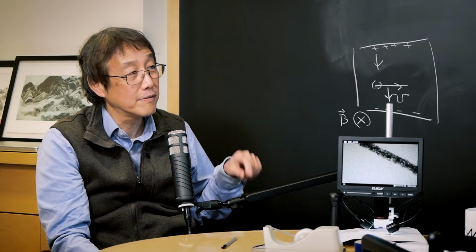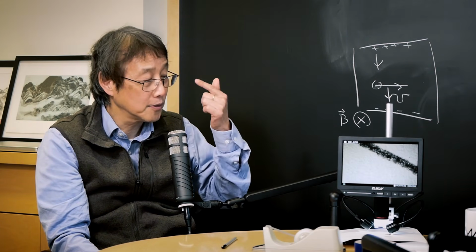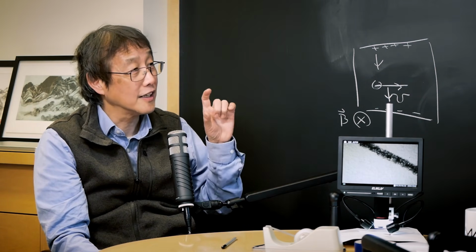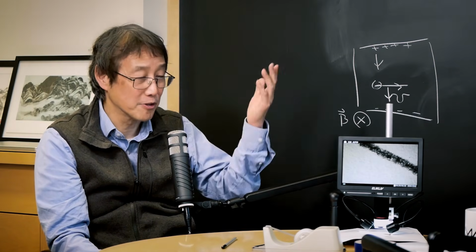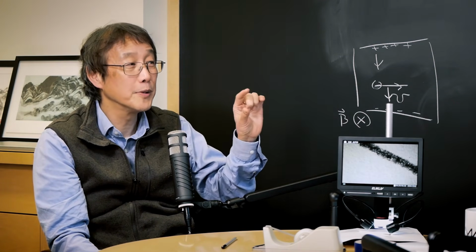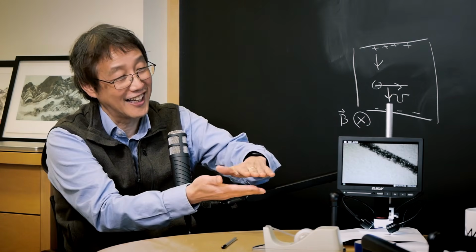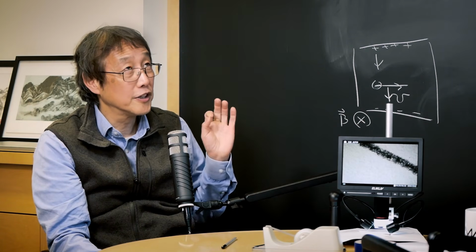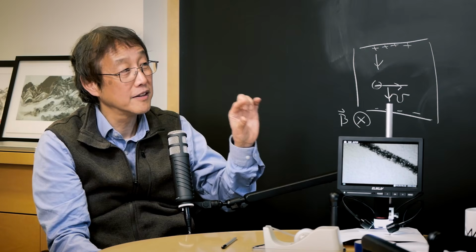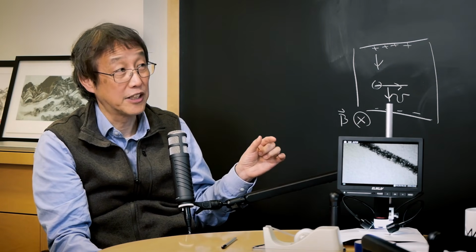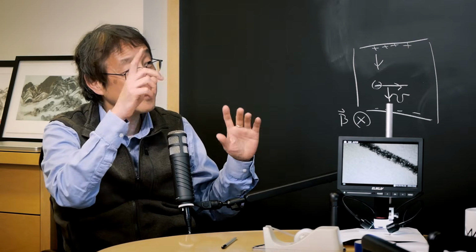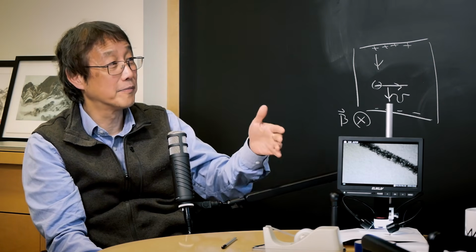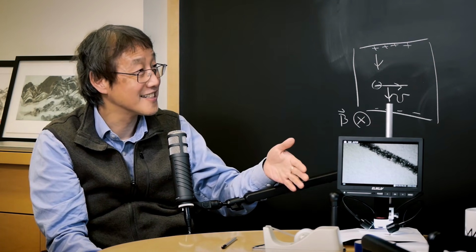The key there is you have to tune your oxide in the right way to keep up with the sensitivity of the eyes to get a really identifiable contrast. And later there is even a paper, I think Geim's group's paper as well, that computes that. This is a simple calculation, right? What is the dielectric constant? The thickness is right. If you just do the numbers, 290 nanometer of the oxide is one. Maybe slightly better if you go to 90 nanometer. But it was reasonably sharply tuned. Within 5 to 10% of that thickness, you get good enough optical contrast. You can identify the single layers, right?